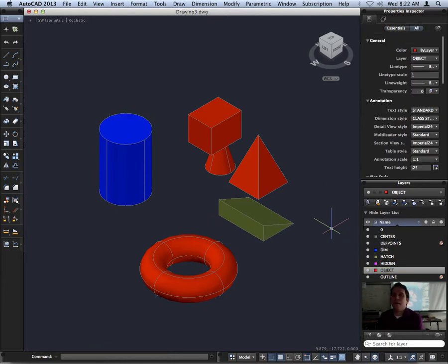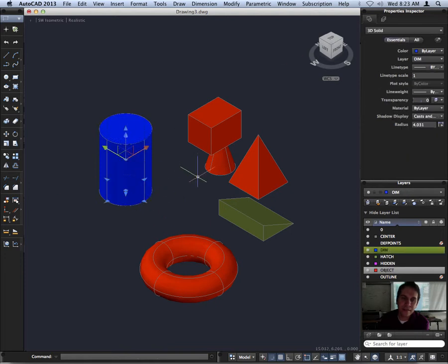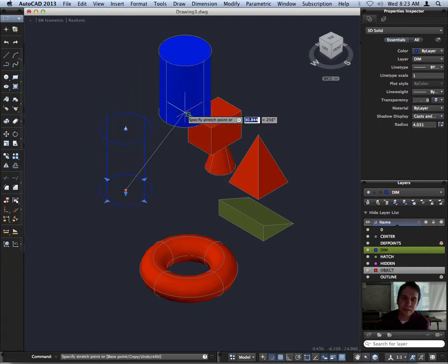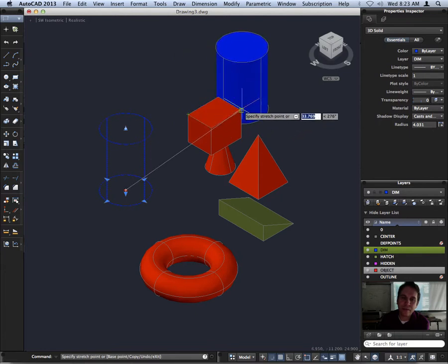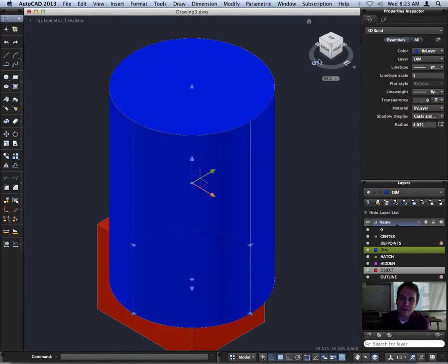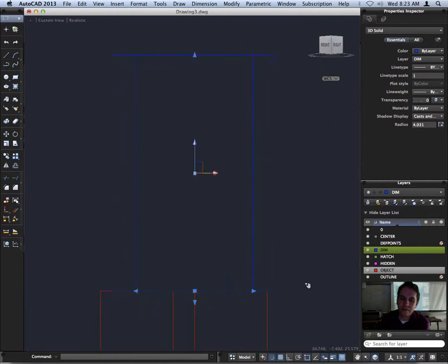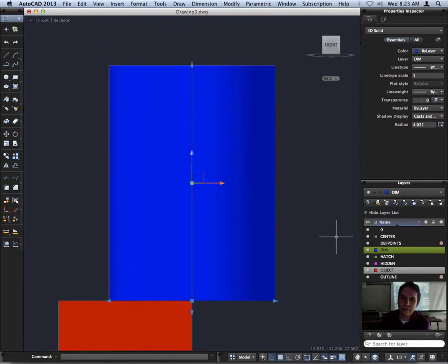Are there any snap points on objects now in this? There is. So you'll notice when you click objects, some things have snappable points and some don't. But I could click this grip point here, and I could snap it, just as I would a two-dimensional object, right to these shapes. And then now when I look, I can see that that is perfectly snapped to that one point.